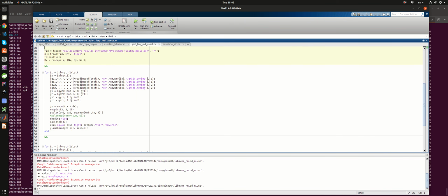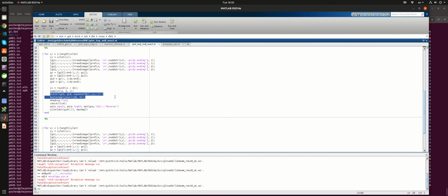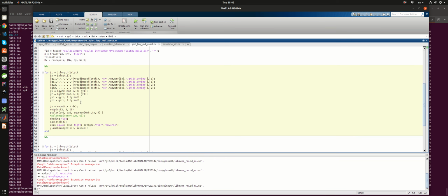And then once mx and my are created, we can just do a pcolor plot, right? And then set the coordinates right. When we do the pcolor plot, the coordinates in the x and y directions have to come from the grid locations, because the gx and gy grids account for topography. Otherwise, it's just going to be flat topography. So those gx and gy files generated by SW4 have the topography information inside of them.